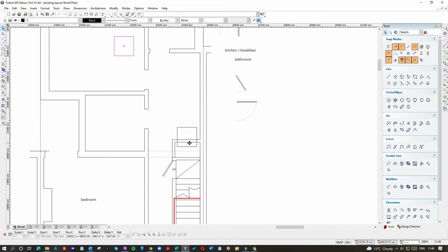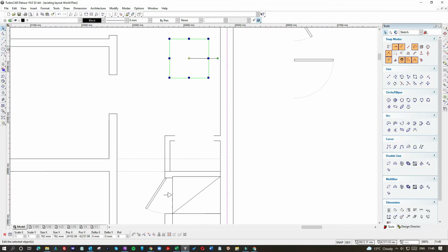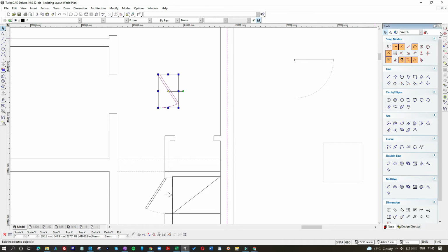That will look good aesthetically. So modify, object trim, and we'll put the door on here rather than on the hallway side where it's a bit less space, harder access. Okay, now because it's a cupboard, we can put this door on it, but not that particular door, as we need one that's handed the other way.